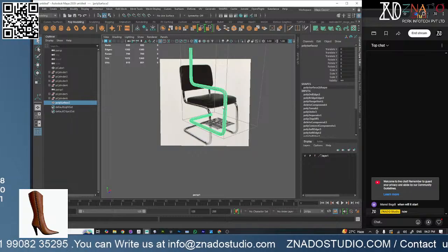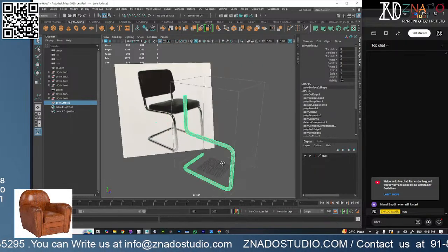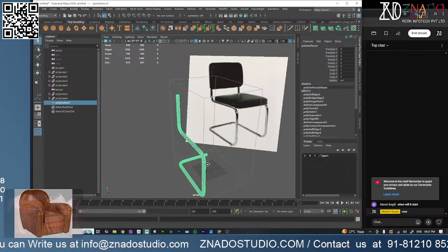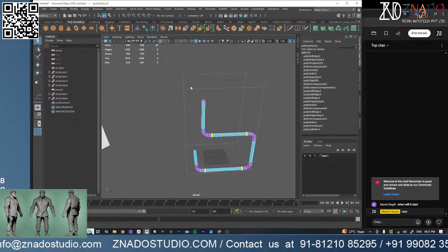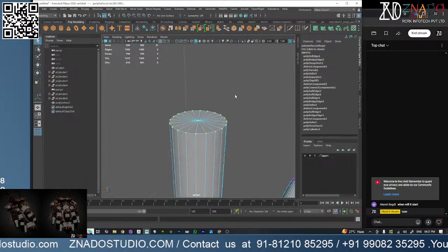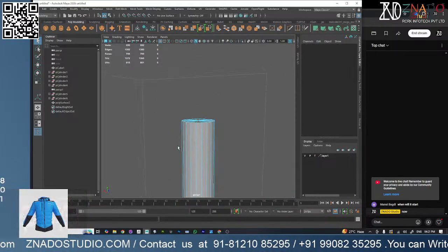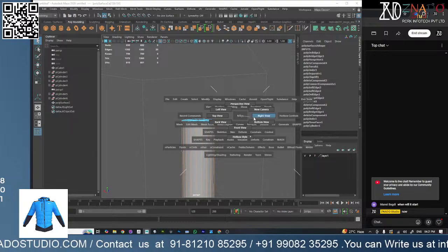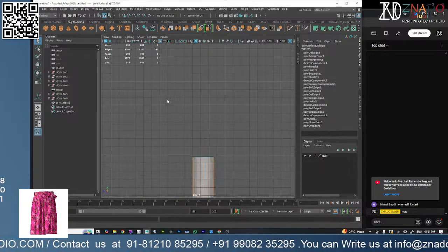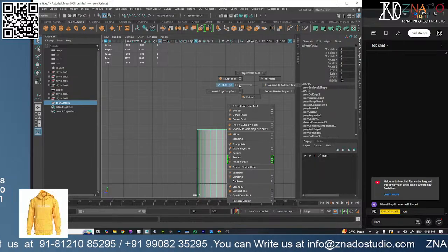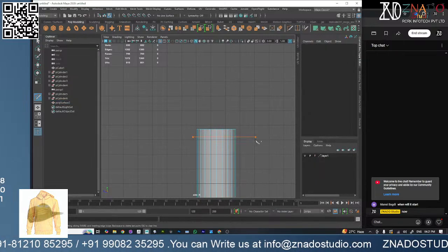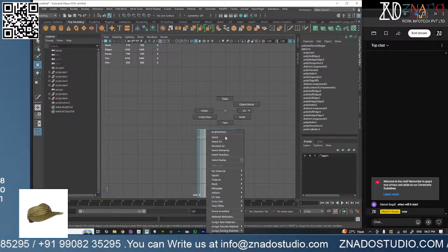Once you have this model done, one side is done, so what I need to do is just mirror this on the other side. Before that, I want to make a cap here so that later when we want it, we can just use it. What I'll do, select, or we can go to side view and use multi-cut here. How to use multi-cut? Select object, Shift right click, and then use multi-cut. Here I'll add a multi-cut. Select this edge,